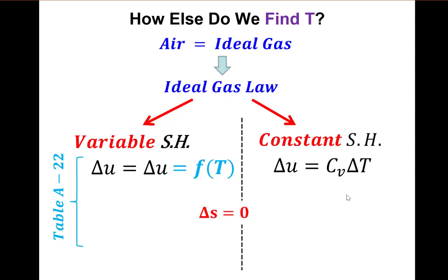The other thing that's really, really important for all the cycles we'll do where air or ideal gases are the working fluid is we need to identify the places where we might have isentropic processes, right? So in internal combustion engines, we're assuming every process is ideal. So if there's no heat transfer, then the process is isentropic, right? So we'll look for those. These are the ones where we're either putting work into the system or we're getting work out.